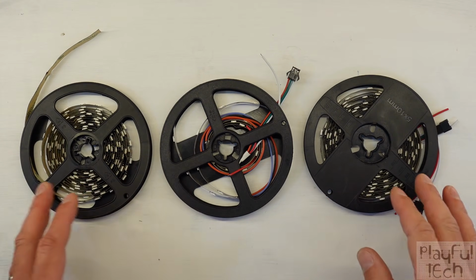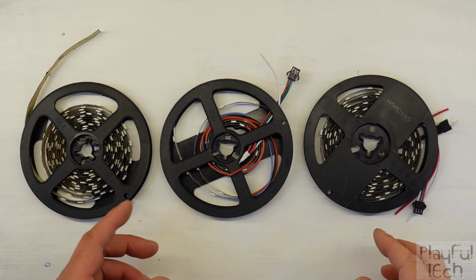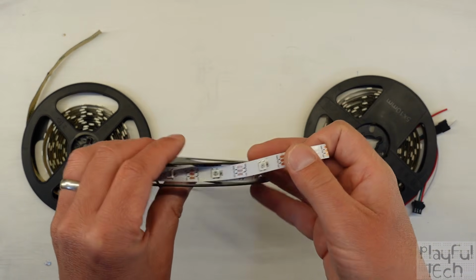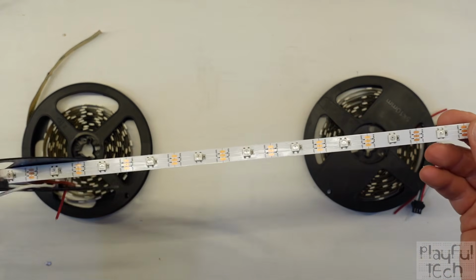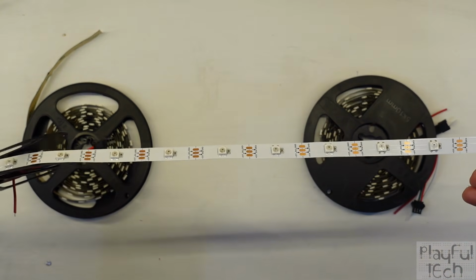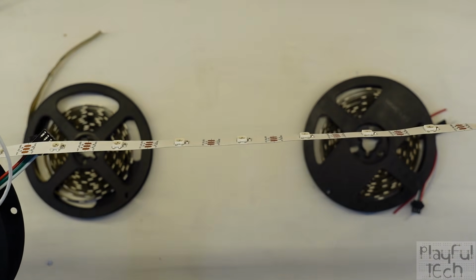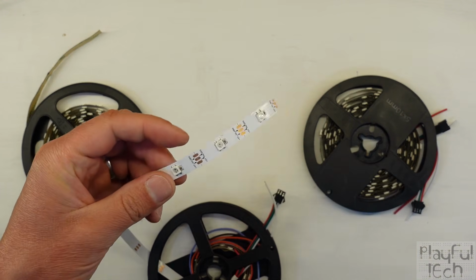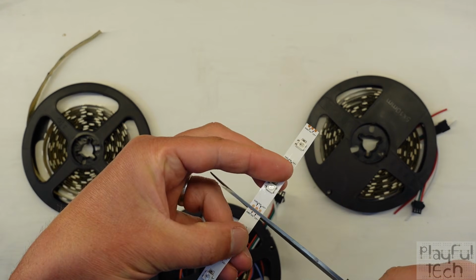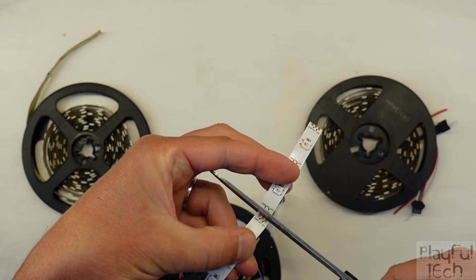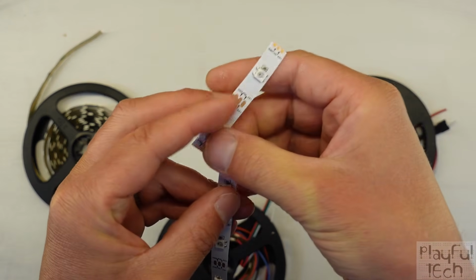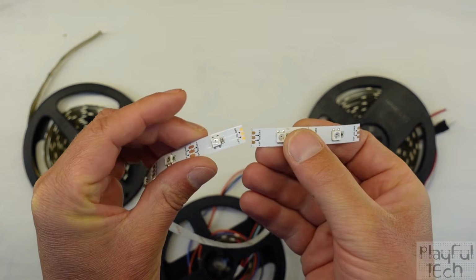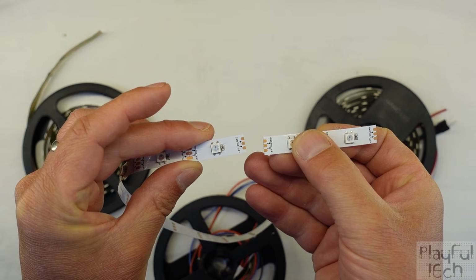Programmable LED strips like this have become very common in electronics projects, but just in case you're not familiar with them, I'll briefly describe how to use them. They come supplied on a reel, and you can simply unravel the strip from the end. You can see the separate LEDs are spaced out regularly along the strip, and in between them there are these copper connections. So when you want to cut a strip down to a particular length, you can simply cut across a set of those connections using a pair of scissors. Make sure you cut straight across the middle of the connection so that you have exposed copper contacts on both the cut edges.